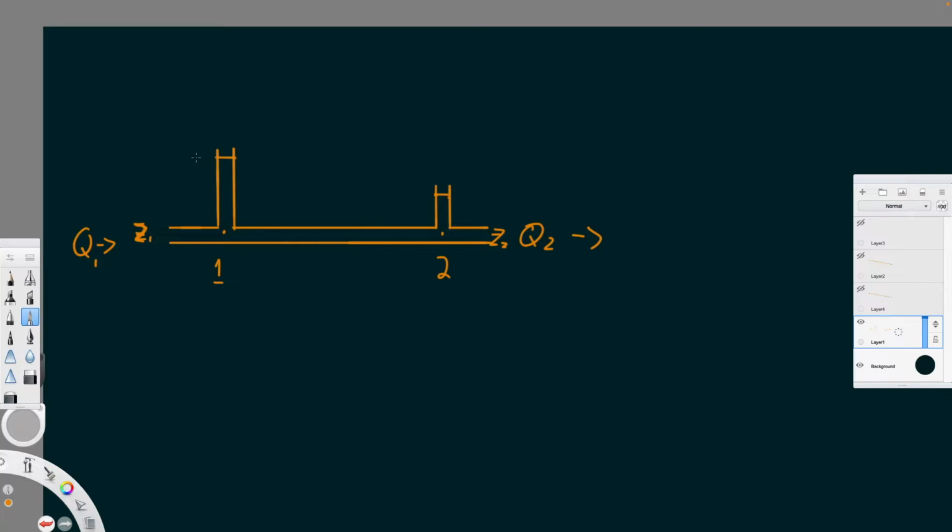Then this height of the fluid is known as the pressure head. So we have P1 over the specific weight of the fluid, and that is going to give us a height that is consistent with the height of this piezometer. And then we'll also, of course, have P2 over gamma.